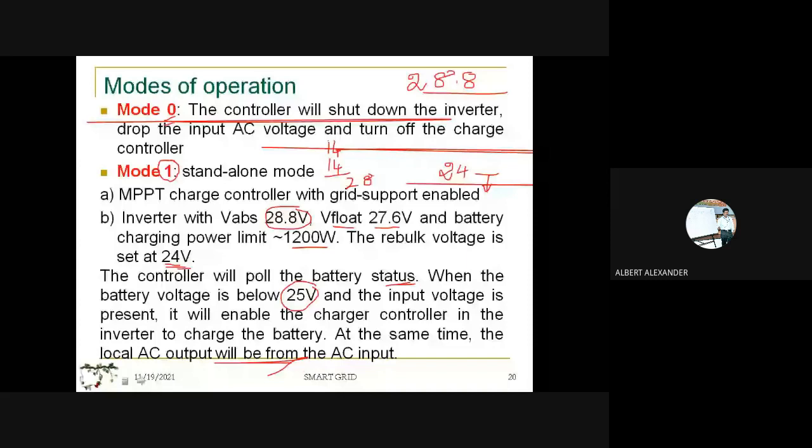And the second one we have seen is with the battery bank. The last one is going to be the grid tie without the battery. Here we are going to enable the MPPT charge controller, and here also the absorption time and the set time are equal to 0. So here the set voltage is fixed as 25.